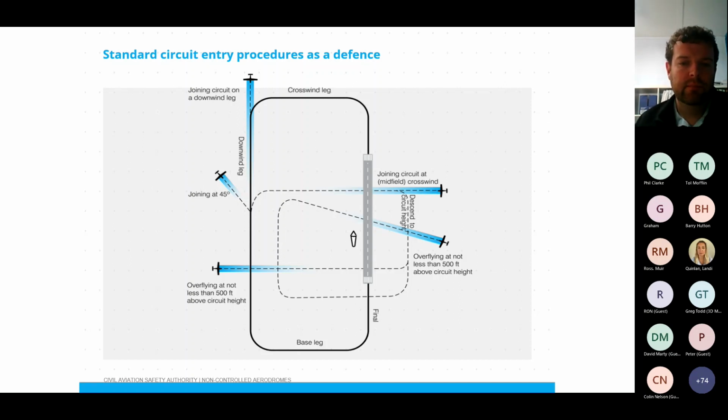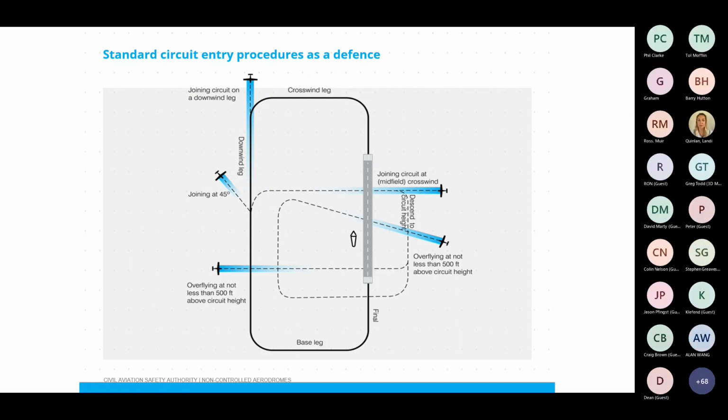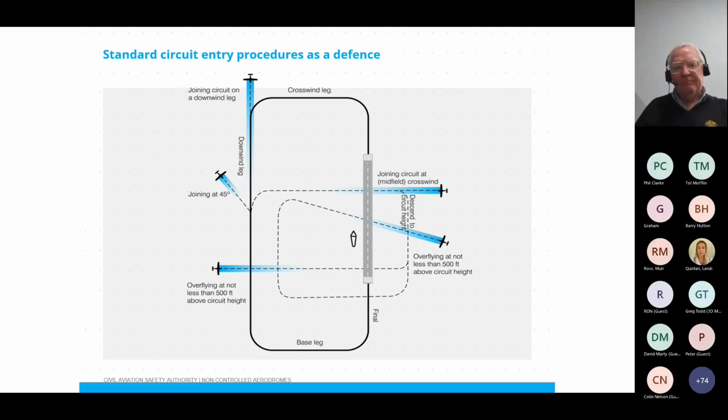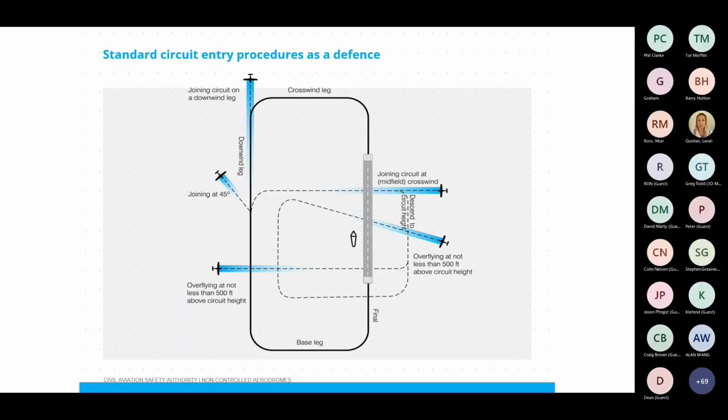Yeah, I think that the last point is a good point. You might very well have a TAF, for example, and you might know what the surface wind is doing and what runway would be used as the duty runway. But of course, forecasts are not always 100% accurate. So, overflying the aerodrome, you get a good look at the windsocks, and you can compare that against what you might have expected the surface wind to be doing. From that point of view, you might need to make a decision about the runway that you plan to at least land on from a forecast point of view.